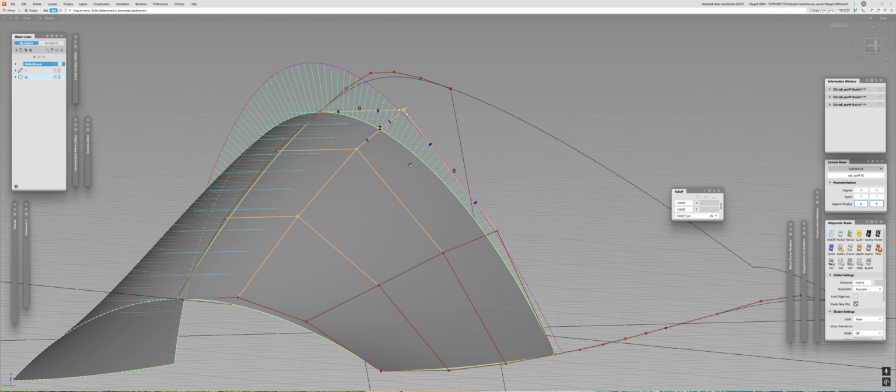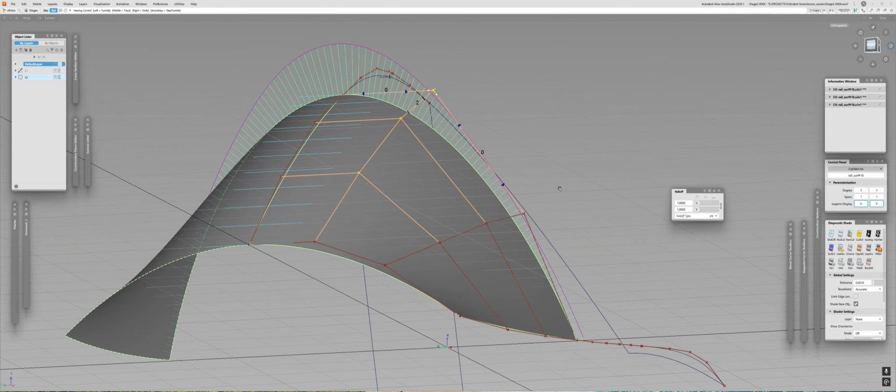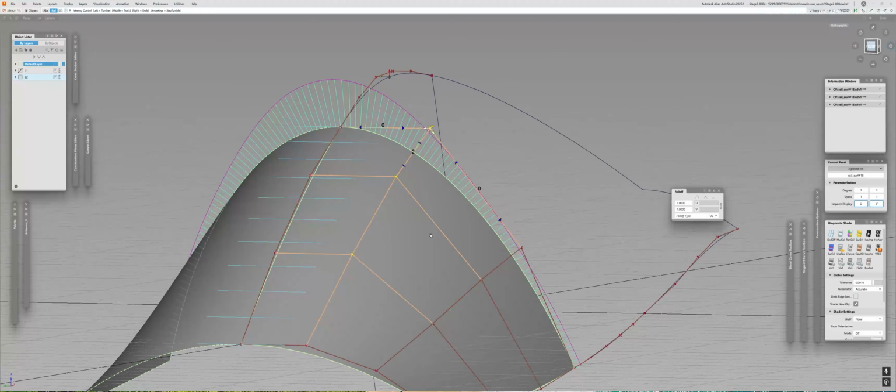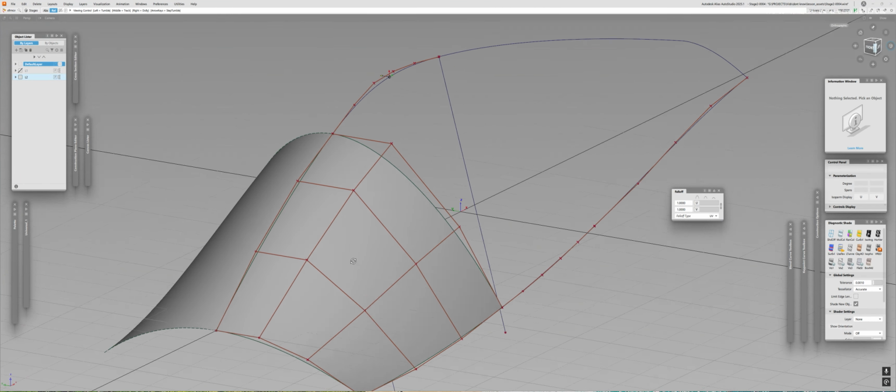So you see, as we already have the proper direction and the proper natural curve, we can tweak it a little bit using the constraints which we already have, right? I have a tangency constraint here, and I have already defined position for all of the CVs, and I can move them as a whole a little bit to slightly morph the shape to achieve the goals I really want. Maybe I want to have a slightly different shape, who knows, right?